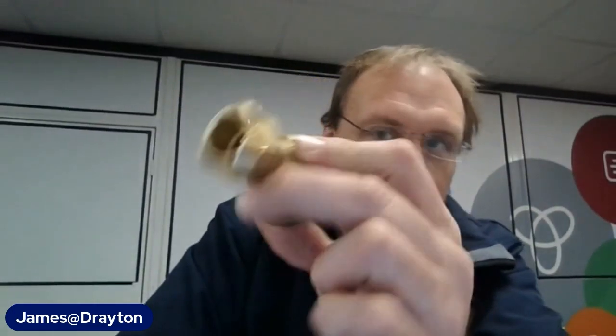Now, if you do it the other way, it means that you tend to get a bit of hammering when the valve closes, because the idea is that with your flow going in on A and out on B, when the spring is pulling it back, you've got the system pressure there, which is going to sort of cushion it as it comes back onto the seat. If you plumb it the other way, you've got the system pressure sort of pushing it onto the seat, so it tends to bounce on the seat and you get a little bit of hammer. So the thing to remember is in on A and out on B.